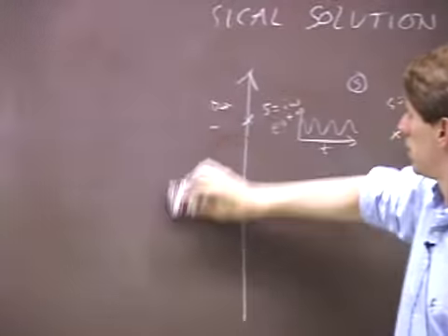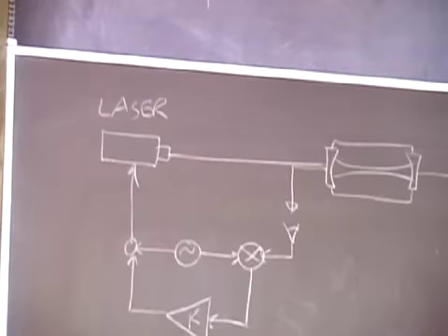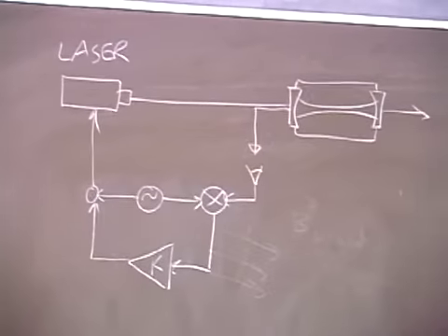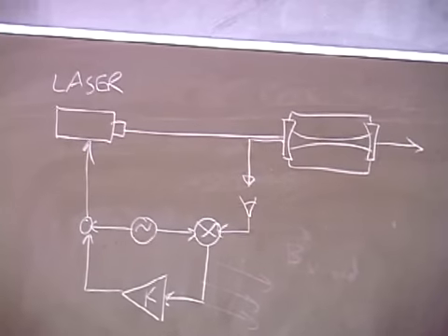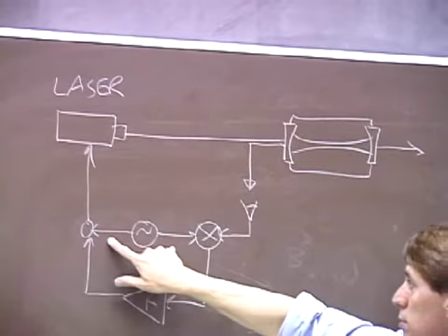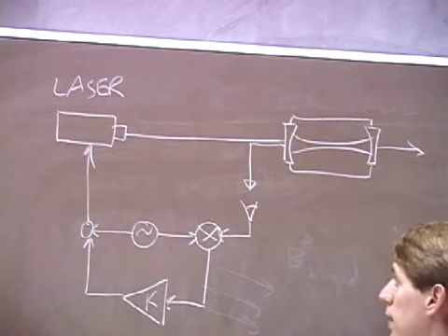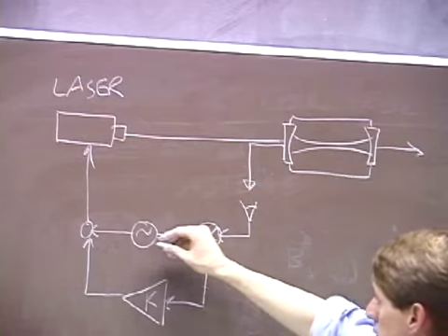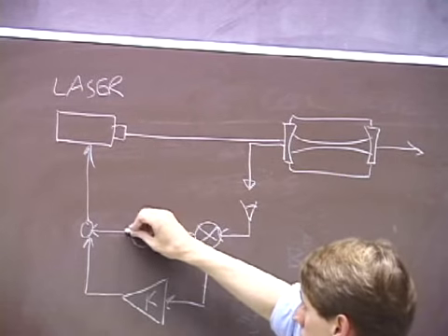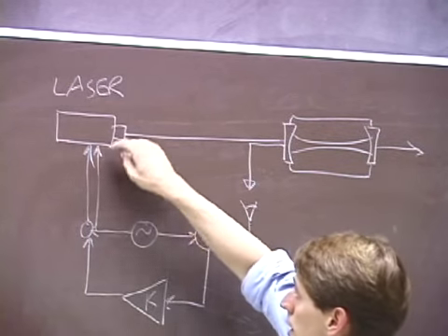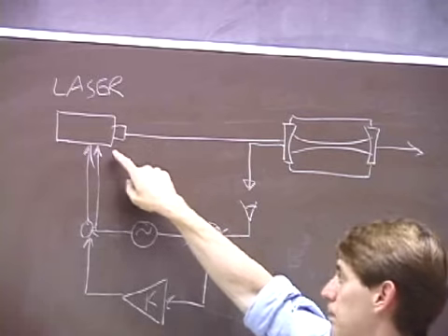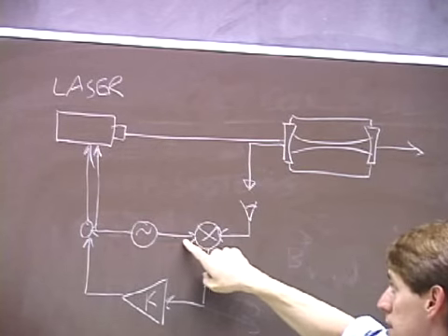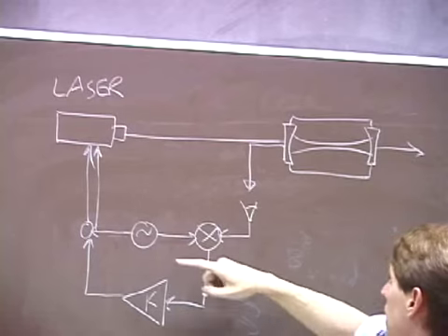Can we just understand the diagram a little bit more? Sure. So your oscillating voltage puts out the same signal in both directions. That's right. It puts out the same signal in both directions. And then just trace where each signal goes. Okay, so this is the oscillating signal. The oscillating signal goes in here and modulates the laser frequency. Another copy of the oscillating signal goes into the mixer.